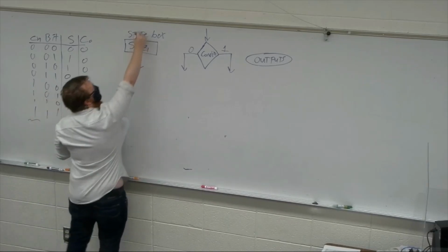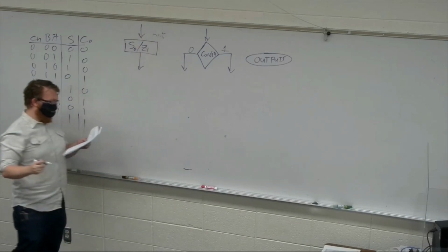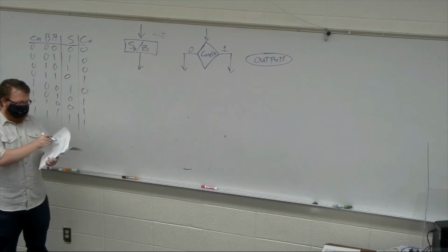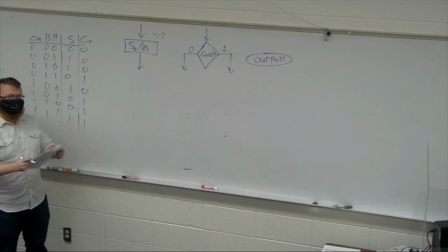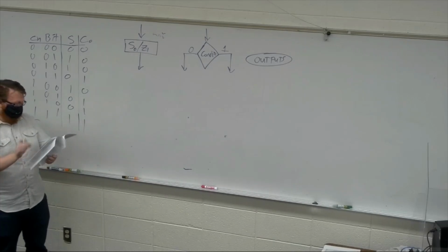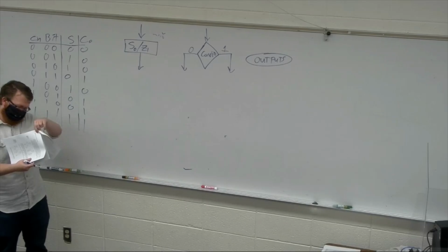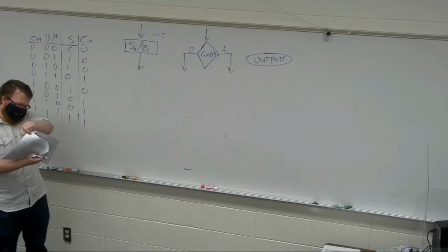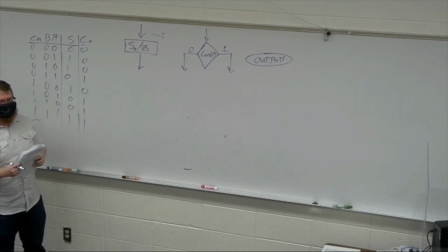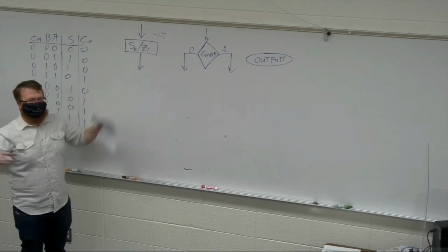So we have to have rule number 1. There can only be one path into our, what do they call these things? State box. Right? No, they have another, SM block, a state machine block. There can only be one input to a state SM block, but there can be multiple outputs to it.